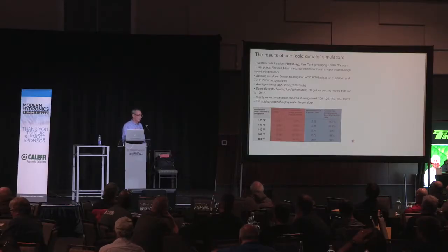That being said, I would still encourage you, if you're evaluating a system, to look at possibilities to add heat emitters to a system. Anything that you can do, even if it's done over time, that adds more heat emitters to the system, brings water temperature down, and ultimately would improve performance. But these numbers were encouraging.